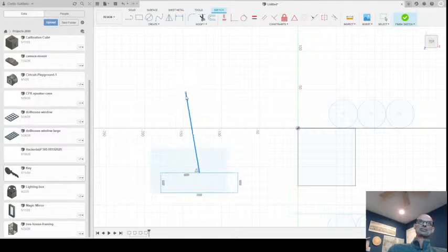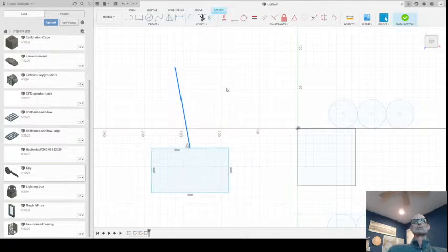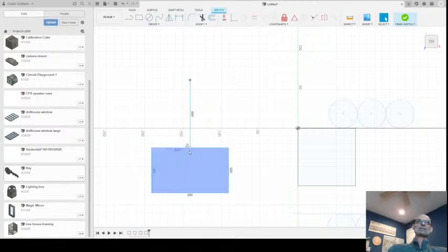You'll notice nothing else is constrained on the sketch, so now it has all this behavior as well, which is unintended. So let's do. All right, so there's the vertical constraint, there's the midpoint constraint, so we've effectively bisected this edge and come out